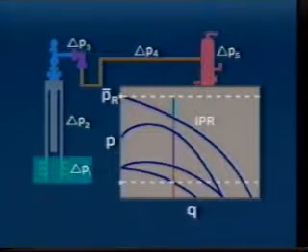Keep in mind that the basis of this diagram is the IPR curve, and that it will change with time. Using this type of analysis, the engineer will select a maximum production rate for each oil well in the field, and then design the necessary subsurface and surface equipment to handle all of the wells producing into a single separator. Developing a performance relationship for a gas well is different from that of an oil well. For details concerning gas well testing, please see your manual.